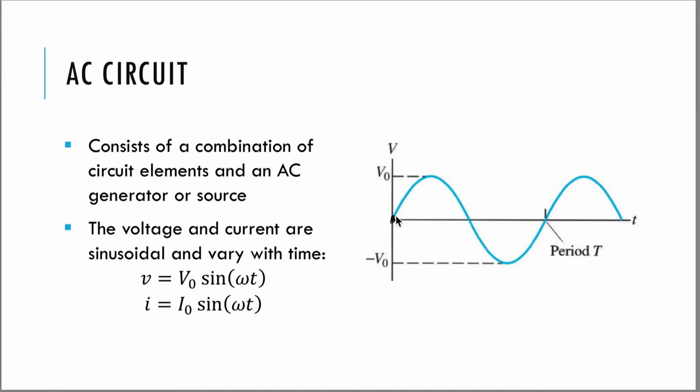At one moment you have no voltage, and then it increases until its maximum value V0, and then it starts decreasing back to zero, and then it becomes negative, right? So what does that mean? You can just pretend that you had a battery in your circuit, and let's consider this a positive voltage, and then after it reduces back to zero, it's as though now the battery's facing the other way. So first the current's going one way, and then the current's going the other way, and it keeps alternating back and forth as the sine function shows.